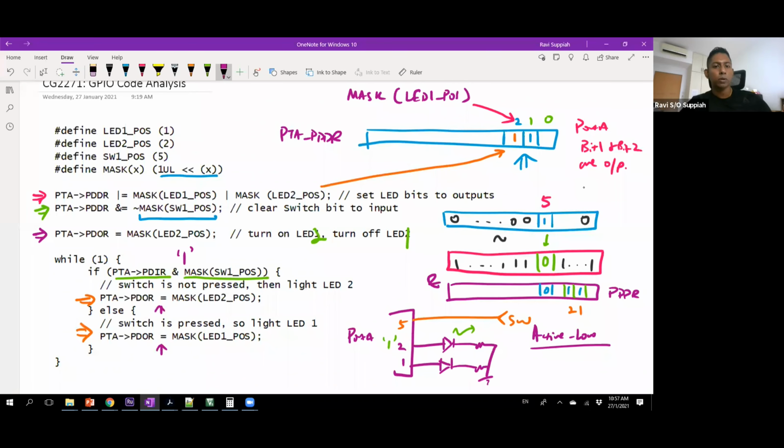If I were to do bit masking, it may be a case where I need to explicitly switch on and switch off each LED. When I directly write, I know that only that particular LED, that particular bit, is set to a 1. The rest will automatically become 0, because when I do the mask function, only that 1 is shifted, everything else is 0.